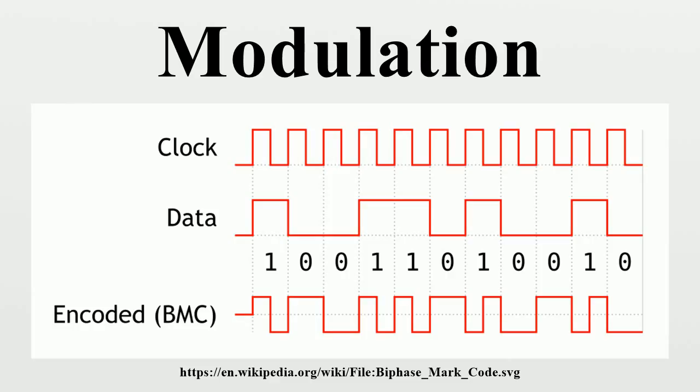These are the general steps used by the modulator to transmit data. Group the incoming data bits into code words, one for each symbol that will be transmitted. Map the code words to attributes, for example amplitudes of the I and Q signals, or frequency or phase values. Adapt pulse shaping or some other filtering to limit the bandwidth and form the spectrum of the equivalent low-pass signal, typically using digital signal processing.